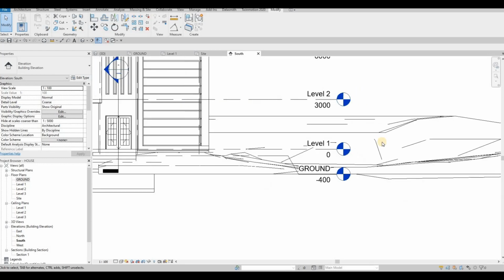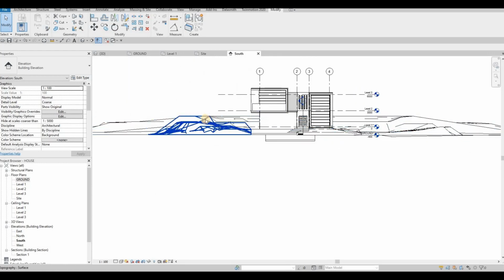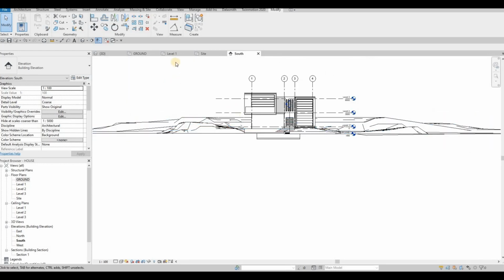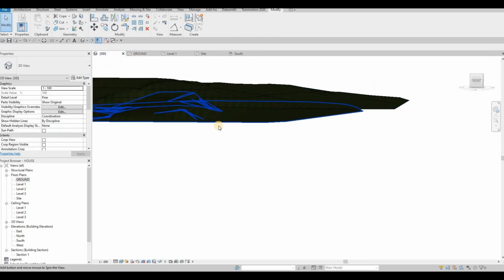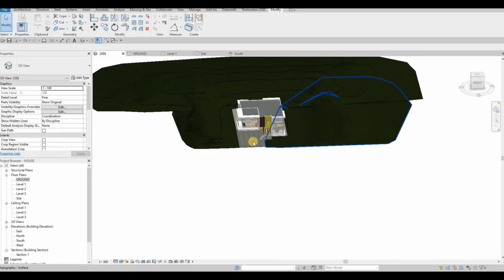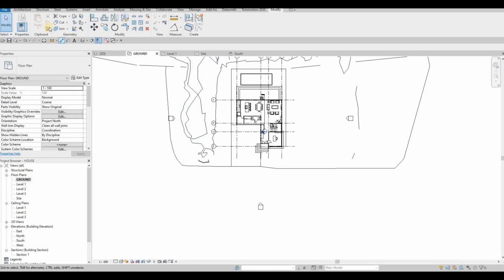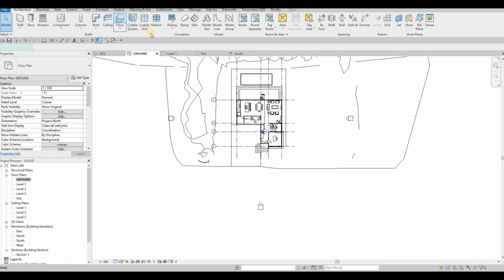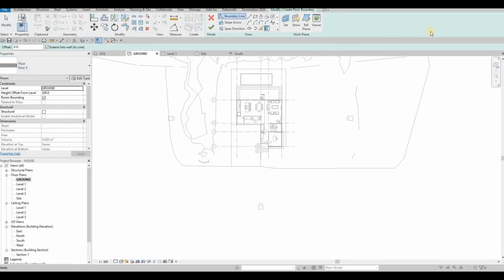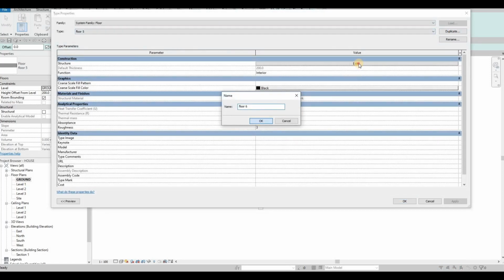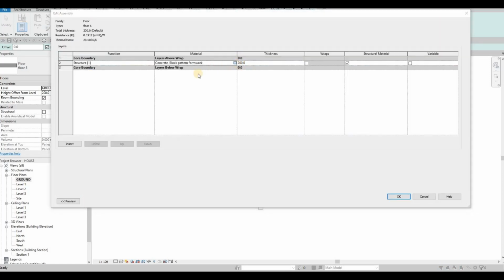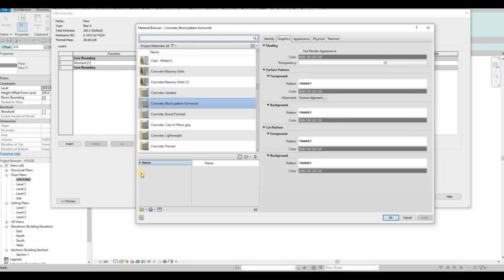You can go to our south elevation, and as you can see, we have those grounding now, and everything is properly aligned like that. We could go to ground now, and I want to add the street, so we need to go to architecture and then click on floor, edit, duplicate floor number 6, and then change this to another concrete material.